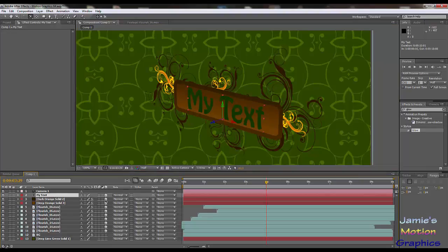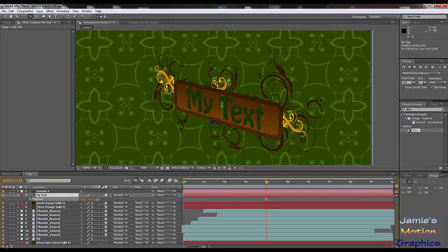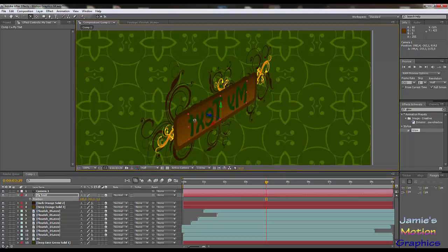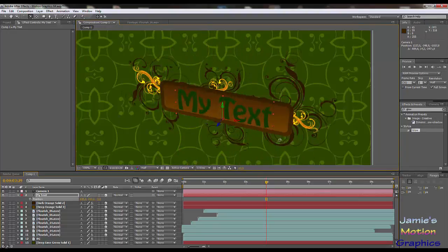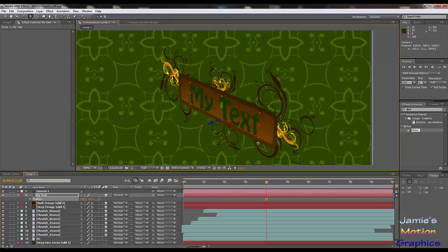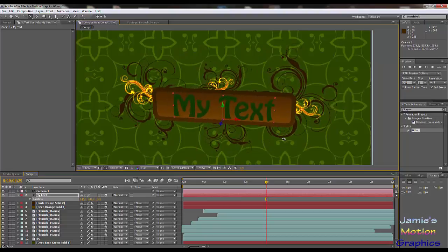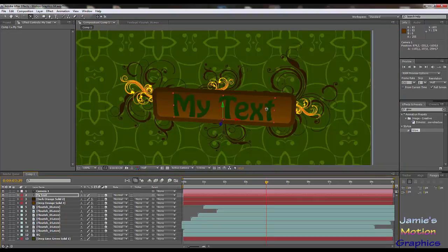First of all, the text. Hit the P for position and just drag it out to the correct side a few pixels. Oh, hang on, let me show you why we're doing that. If we go behind this, there you go, you can see the text. Now if I move this to -5, which is like 5 pixels, which is not a whole lot, you can't see the difference in where it is and where the plate is. So it doesn't show up on the backside, which is a huge thing for your final design, because otherwise when you rotate you will see the text mirrored on the back of the plate, which doesn't make sense at all.